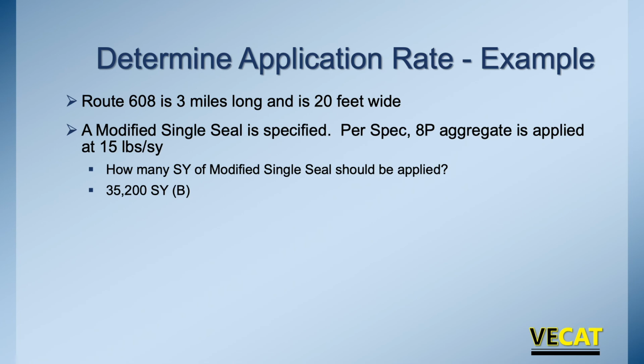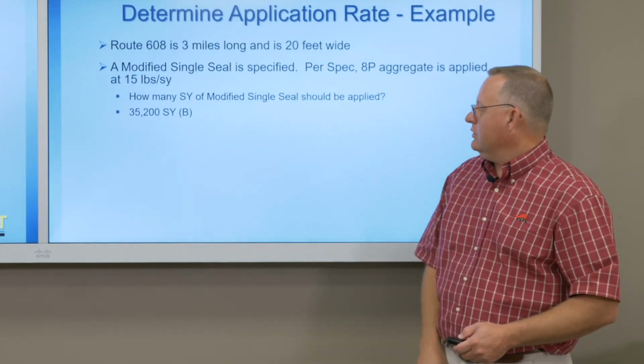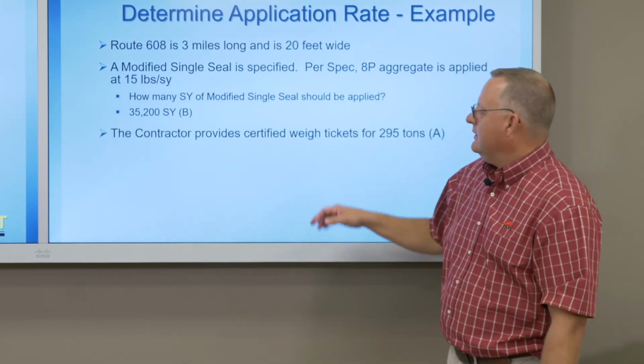If you do the math, it's just 3 times 5,280 times 20 feet wide divided by 9, which will give you 35,200 square yards. So that's the area that we're looking at. That's how many square yards are going to be applied to.